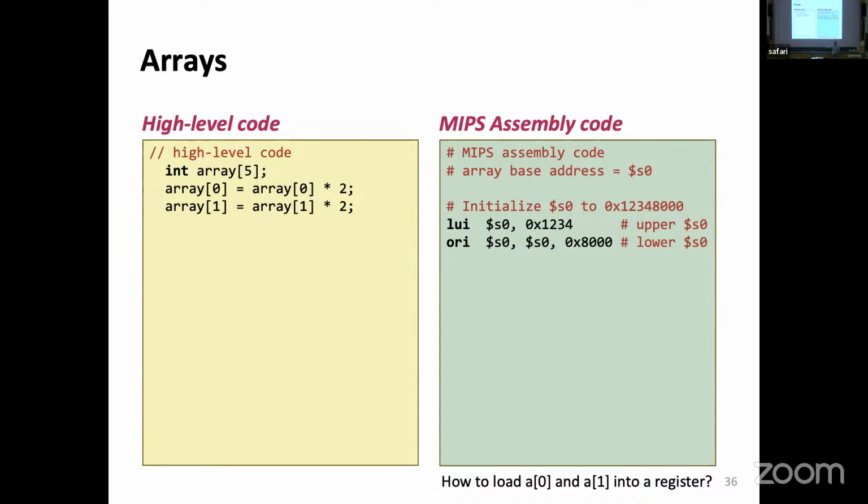So you have a 32-bit address, and you need to load it to something. The compiler will emit these two instructions and divide the address into two. So my question was basically that it's the job of the compiler to do that, because here there's a constant address, there's not a variable or something, and then you just divide it by your hand. I mean, it's done by somebody else, not in the assembly code itself. My question is, is there like a specific pre-coded function where we just give it two bits and get 16 and 16 or something like that?